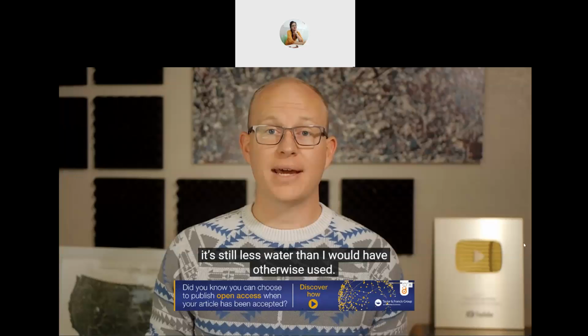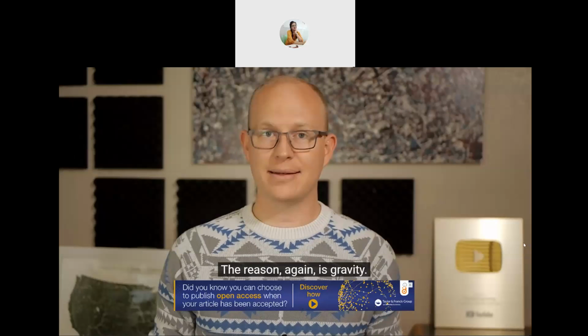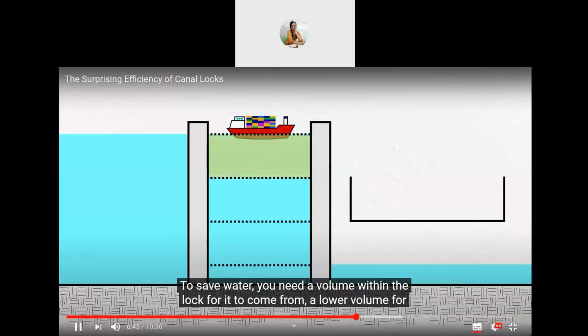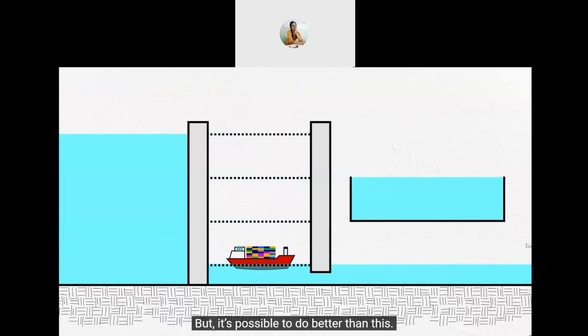In fact, if the water-saving basin is the same area as the lock, you can save exactly 1/3 of the water. The reason, again, is gravity. Water doesn't flow uphill, it always has to be going down. To be able to save water, you need a volume within the lock for it to come from, a lower volume for it to drain and wait in the side pond, and finally, an even lower volume within the lock for the saved water to go. That means the best you can do with a single basin is to save 1/3 of the water that would otherwise be lost. But it's possible to do better than this.